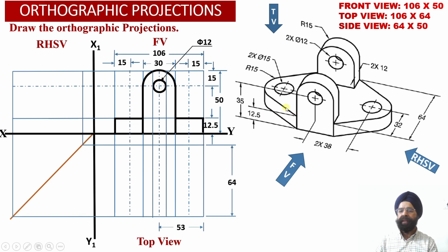And now we can check the portion of the horizontal web which is lying onto the left hand side of this particular vertical web, and this portion of the horizontal web which is going to lie onto the right hand side of this vertical web. So both of these portions will be visible to the observer as apparent shape projections into the front view projections as rectangular projections over here. So we can check this is a big surface over here. This is also a big surface over here.